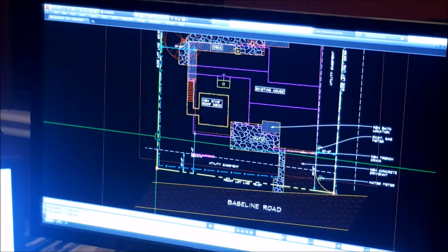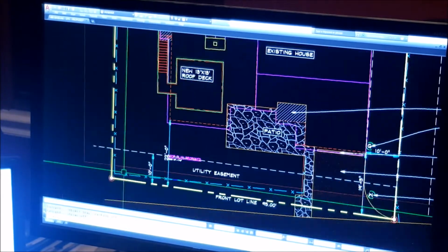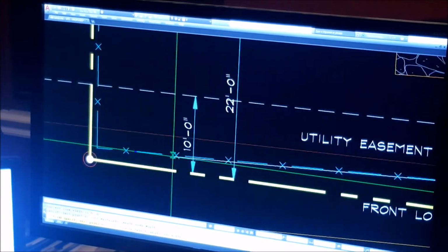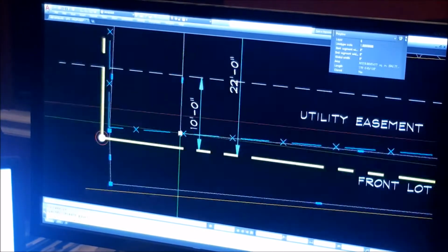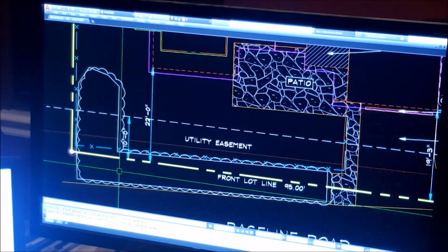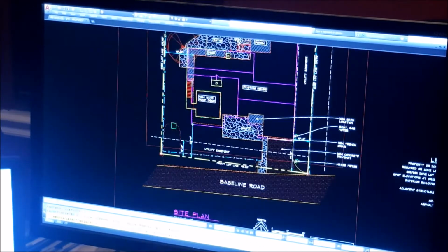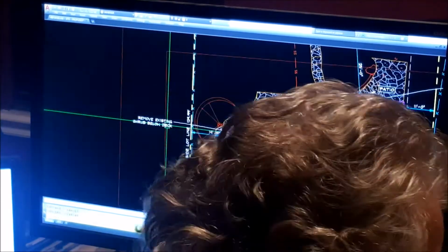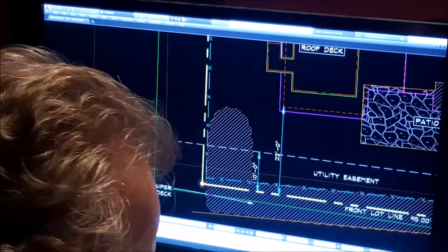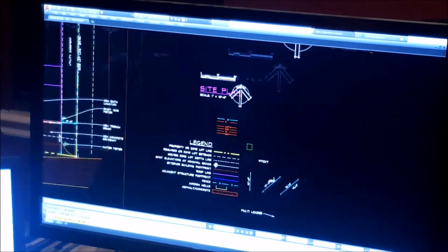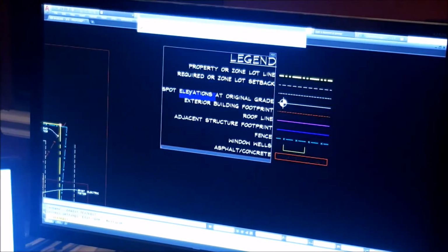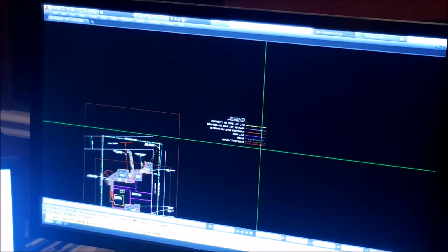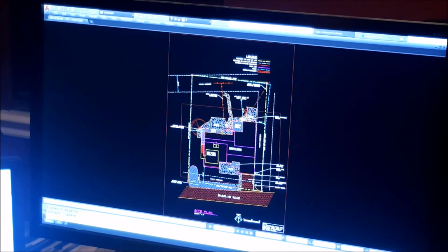So what I did was I put everything in place this time and then hatched it underneath there. So you can see a little bush was hatched in there. This is another shrub I'm putting in. Just using a polyline and converting it to a cloud, and then just hatching the cloud. Caps lock wasn't on when I started that text, so I just converted everything to capitals using the text editor. These are items I didn't need in the site plan, so I condensed this down so that it was more refined, a little bit leaner, meaner.